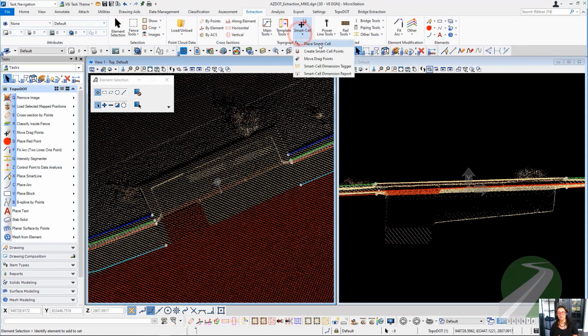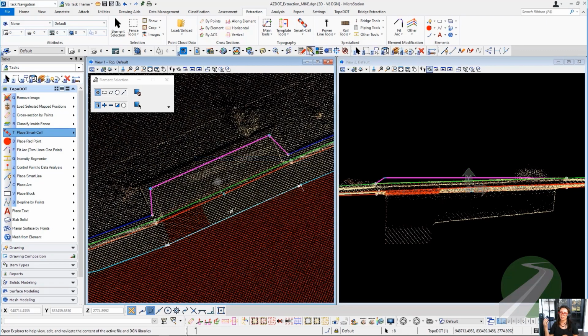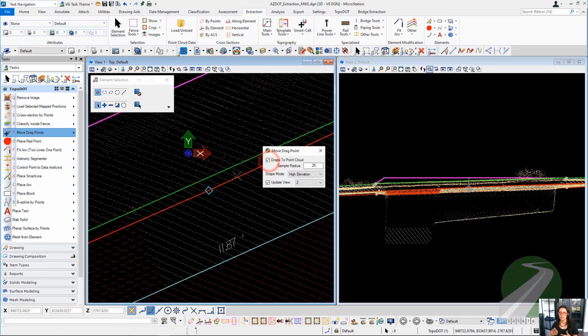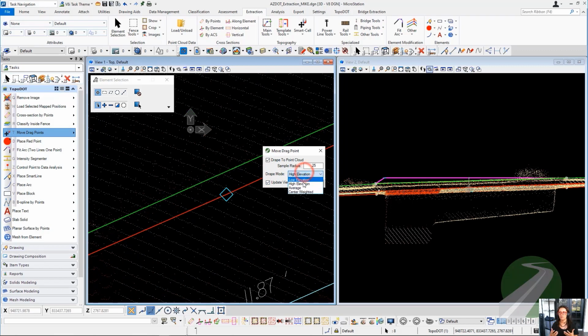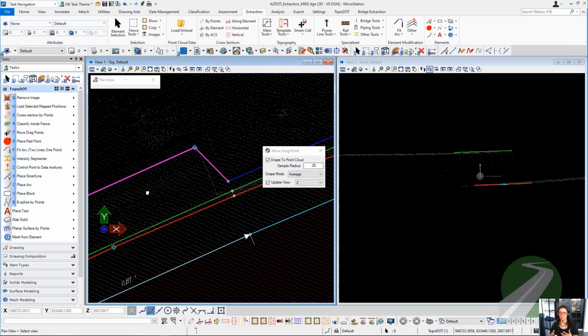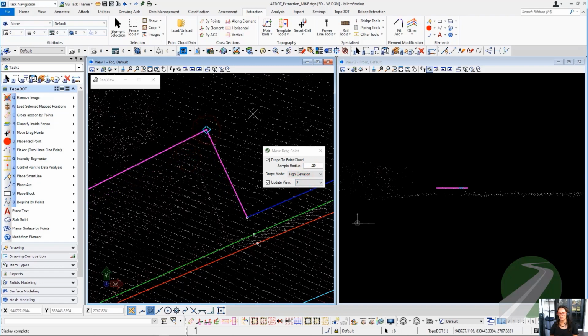We also have a ton of tools that make your break line extraction a lot simpler. In this case, for example, we have something called a smart cell, which is a template for features that happen in between your break lines and are constantly recurring, like ramps, drain inlets, and driveways. With this template, we just identify what's changing, like what edges need to change, and those are the ones that we move or adjust to current conditions.